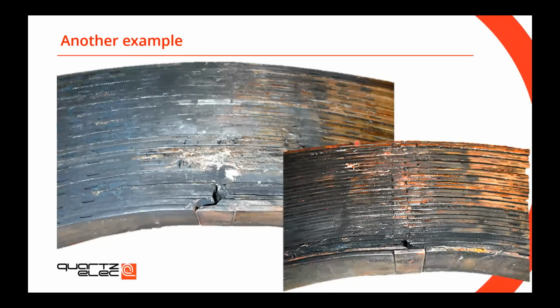So another good example, it's actually a very good example because this will mix everything I just said. If you notice, you have an interturn fault on the bottom coils because, if you remember, the retaining ring will be sitting on top here. So we can tell that the interturn fault here is far away from the earth potential, so it's not as critical as the one that would be here, for instance.